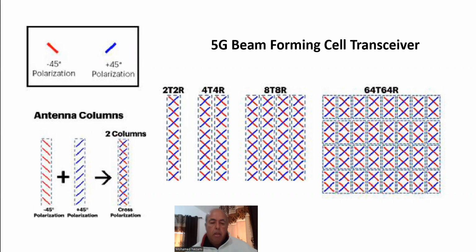We're not talking about the handset. If you look at the handset, usually for millimeter wave, they've got 4 arrays, 2 on each side of the phone, away from the places where you usually hold it with your hand. Usually it's on this side or this side. And you can check those out. So those are mostly 2 transmit, 2 receive, or actually 4, because there's 4 elements in there. Each one is dual polarized.